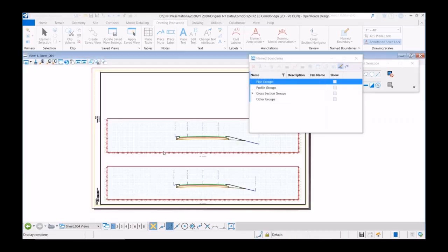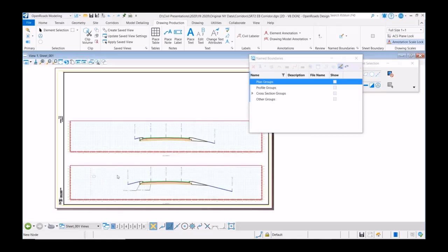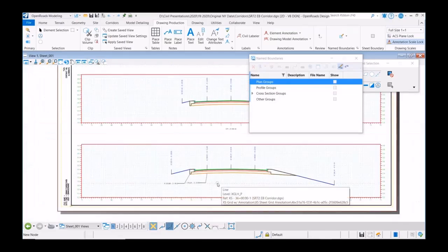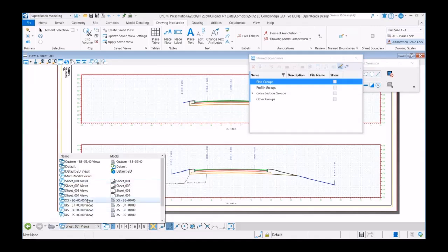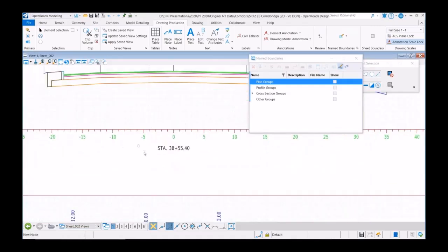So now I can resheet those, and I should see, not sure what sheet it's on, I guess we'll go look on sheet 1. For 1, we still have our drawing model intact. We didn't have to delete that, but we also should have the new cross-section slice on a sheet as well.